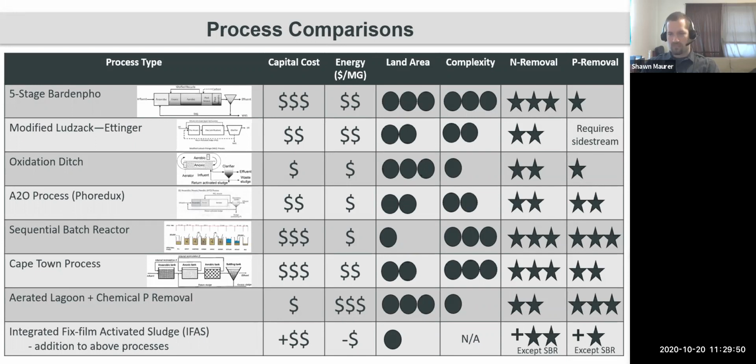Again, if you want to do phosphorus removal with a process like that, usually it's done with chemical addition afterwards, with subsequent filtration or settling out in a clarifier. But you could also do an anaerobic basin ahead of that oxidation ditch and add that anaerobic stream right at one of your aerators to make sure that it gets oxygenated properly, and then move that through the process.